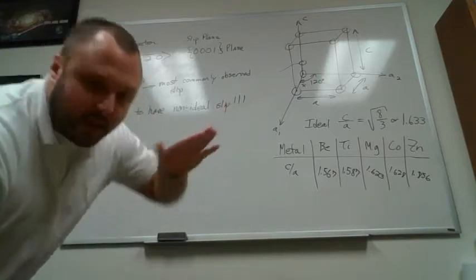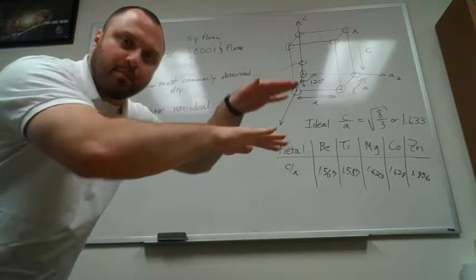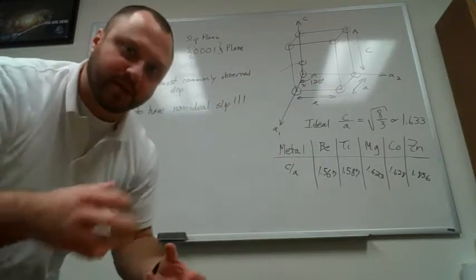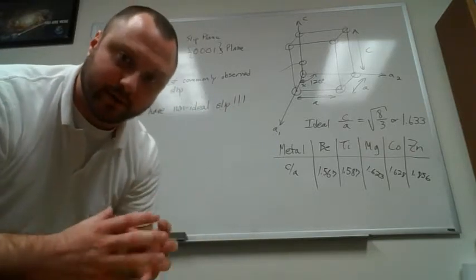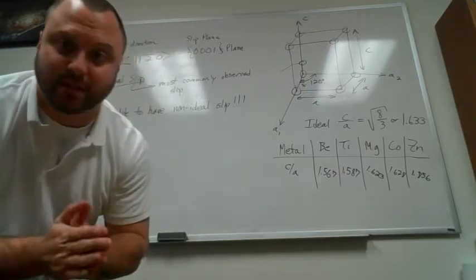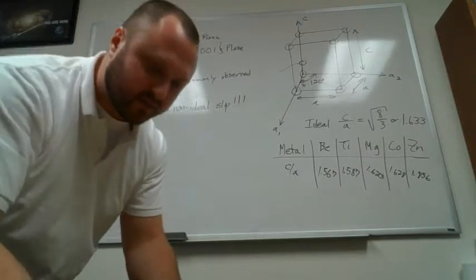But if you look at those basal planes, they're stacked on top of each other. But when we're trying to plastically deform something, we're trying to give it an arbitrary shape change. And we need to have slip along all different planes to give us that arbitrary shape change. And it turns out that it's very hard to have that with just basal slip. You need to have some other mechanisms active. Okay? We'll derive it later, but it gives you a sense of what's happening.